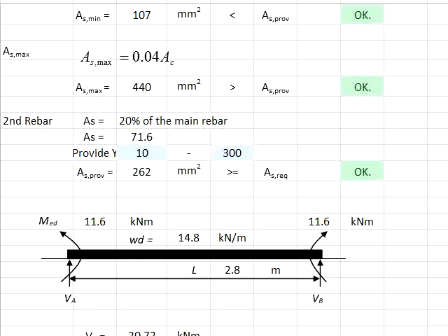It also helps to keep the main reinforcement bar together, especially when the workers on site will need to tie the primary and secondary reinforcement bar together before the casting, in order to ensure all the reinforcement bar are at the right positions during the casting.